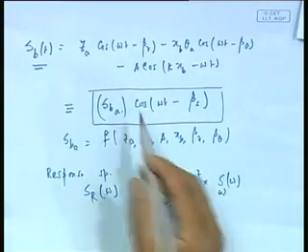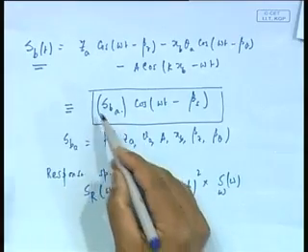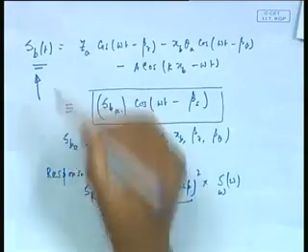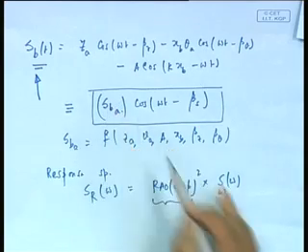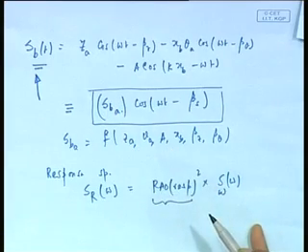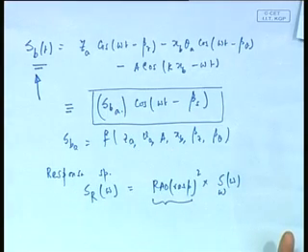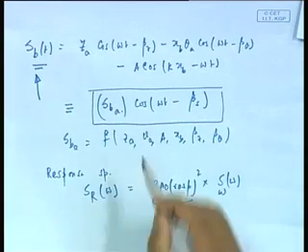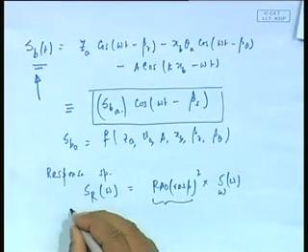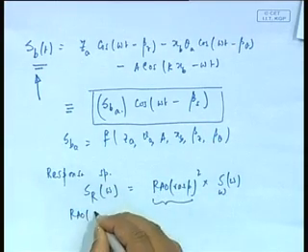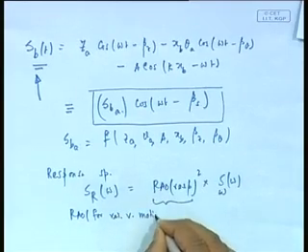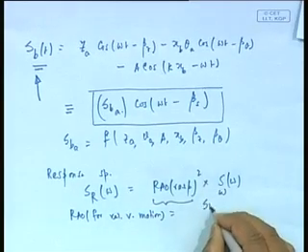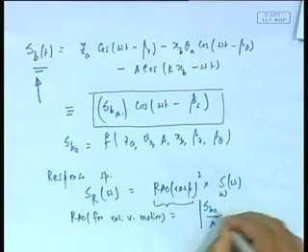In this case, I want the response spectrum for this particular quantity, which means I have to take the RAO to be S_BA divided by A. That is it, there is nothing to it. So the RAO for relative vertical motion is nothing but S_BA by A.